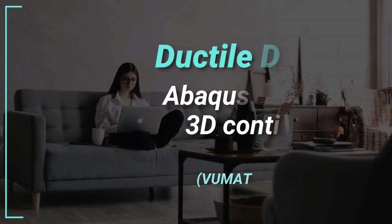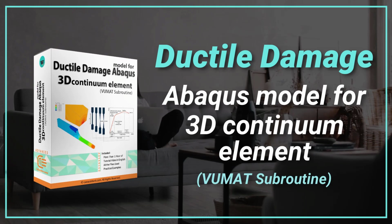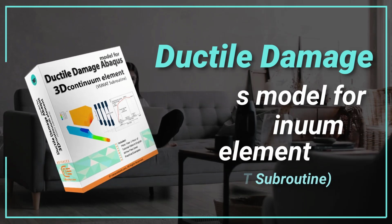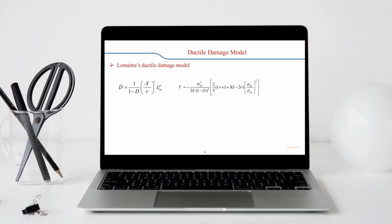In this package, the continuum damage mechanics framework for ductile materials is implemented and developed in Abaqus by VUMAT subroutine. Now we are going to the Lemaitre damage model. The Lemaitre damage model is used for ductile materials.